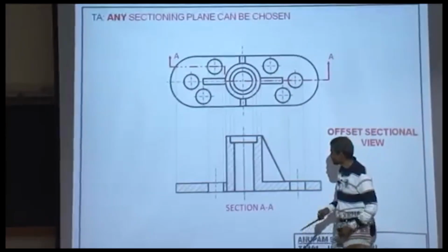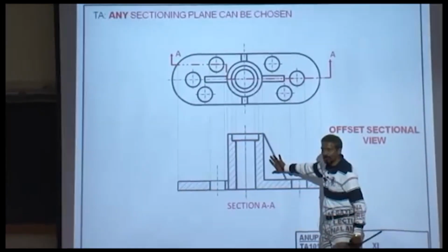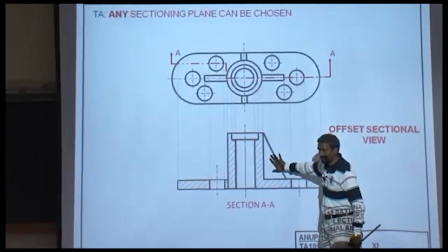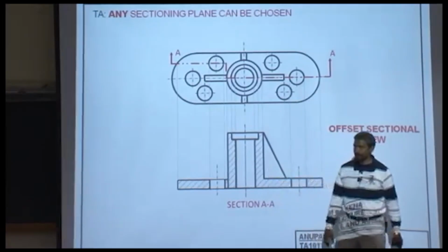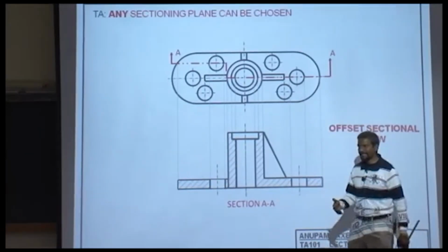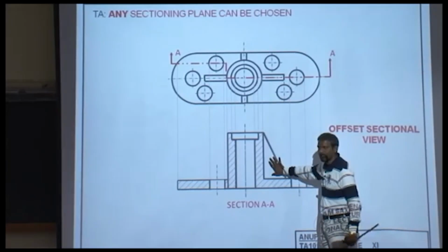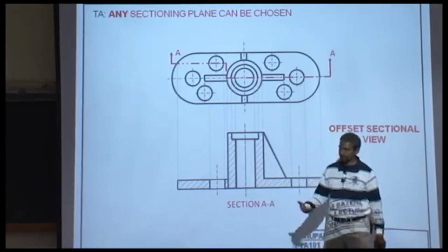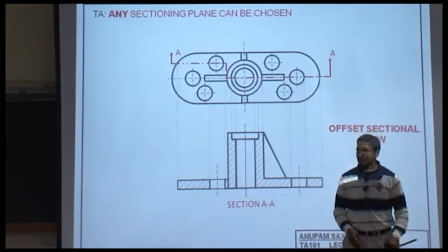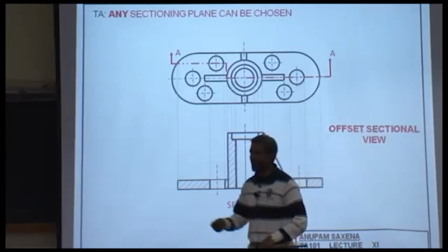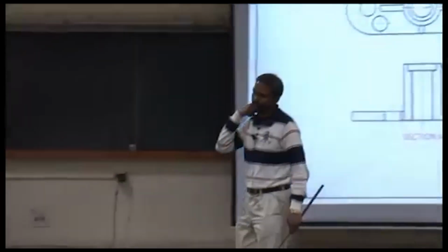Assuming that this is not there, would it be visible then? So when you're sectioning, just assume that supporting elements are not there. Section and then add the supporting elements later. Okay? By convention. I'll talk about that a little more.